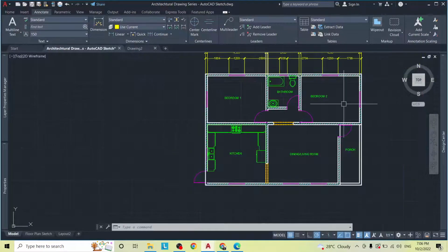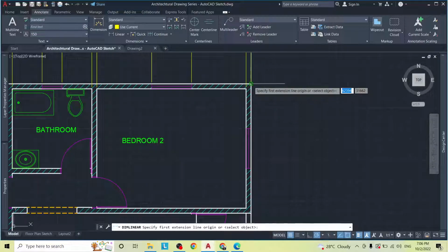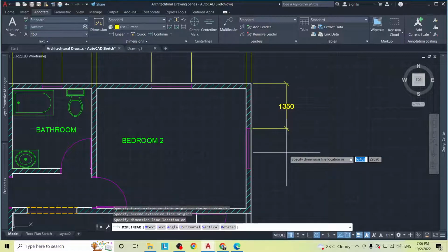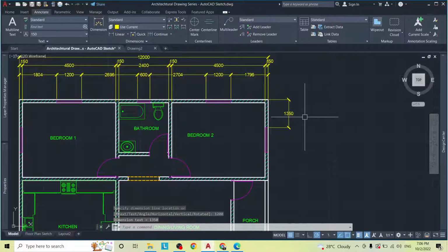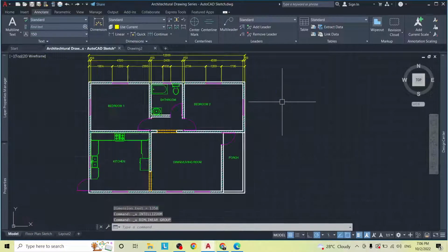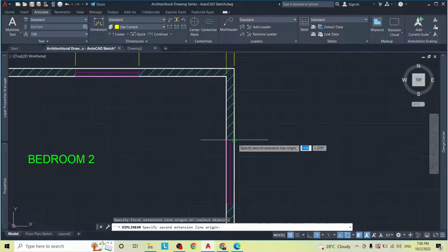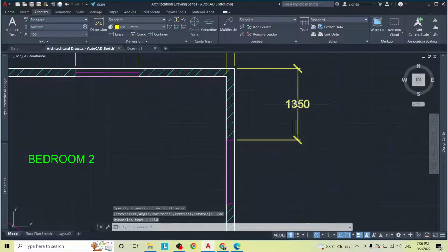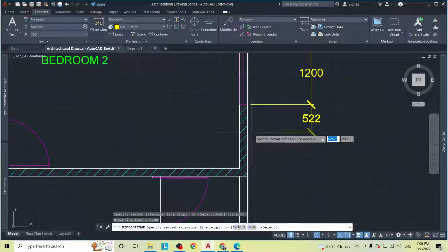All right, so let's just finish this whole thing up, and then this drawing is going to be done. So linear tool again, let's do this side. Click the end wall, the first row is dealing with the wall. Bring it off 1200, enter. That does not look like 1200. It looks like it just went where my mouse was. So if I come here, type 1200, hit enter, there is 1200. Alright, now we're going to continue that point.